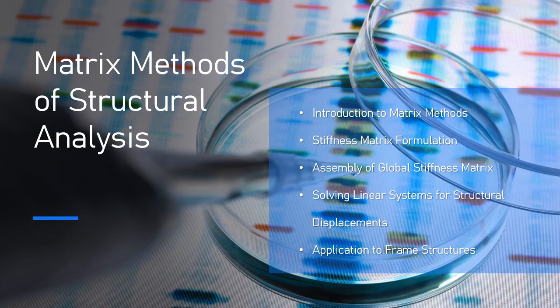3. Matrix methods of structural analysis. Solving linear systems for structural displacements. Once the global stiffness matrix has been assembled and boundary conditions applied, the next step in structural analysis is solving the system of equations to find the displacements of the structure under the applied loads.